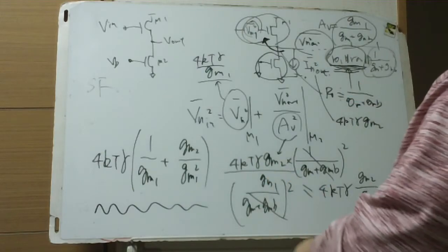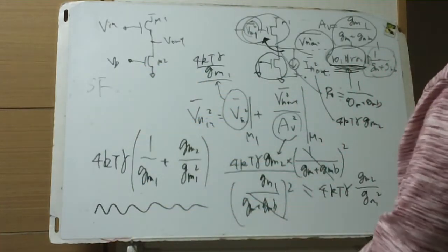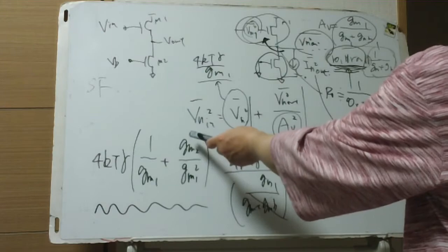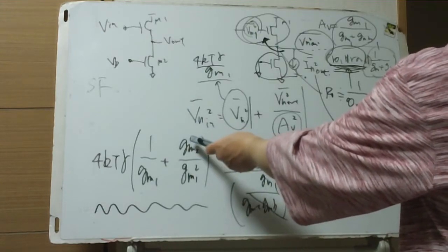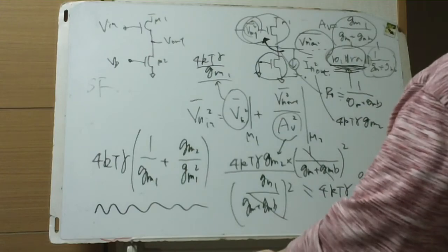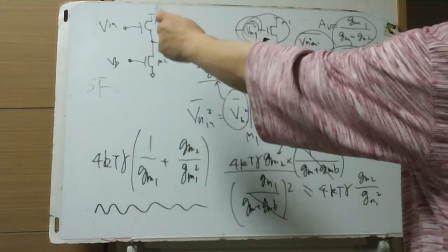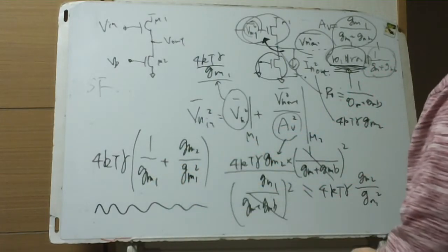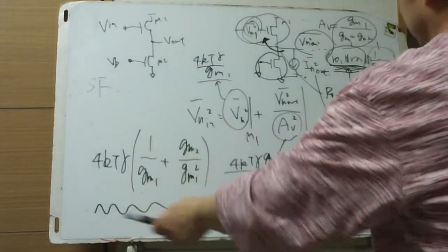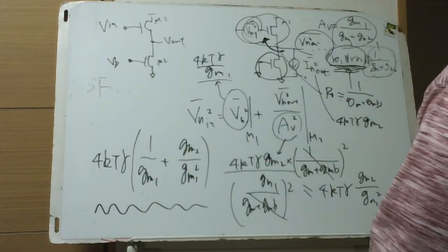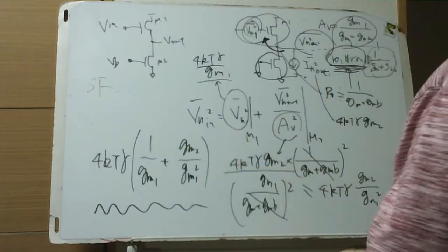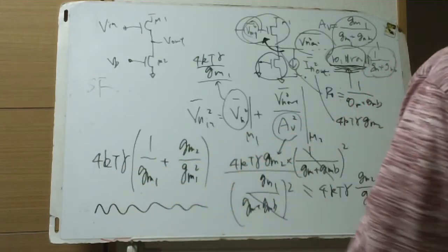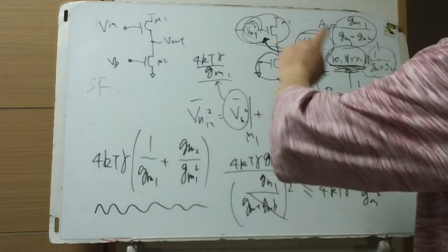Decreasing input referred noise for source follower and common source is the same. For common source amplifier, making the p-channel conductance as small as possible for current mirror biasing, and the amplifier's input conductance as high as we can, making both realizations leads to lower input noise, and of course output noise.